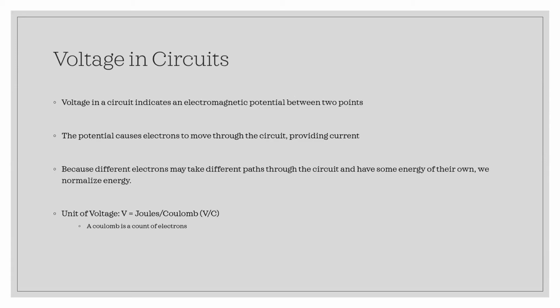Okay? And then just like in the previous example where we installed a catch halfway down the hill, we can define zero voltage where it's most convenient for us. In a DC circuit, where it's convenient for us is often at the lowest point of energy in the circuit, so we don't have to deal with negative voltage. But know that negative voltage is a thing that is allowed in circuits, and it's in fact quite necessary to deal with alternating voltage circuits or AC circuits.